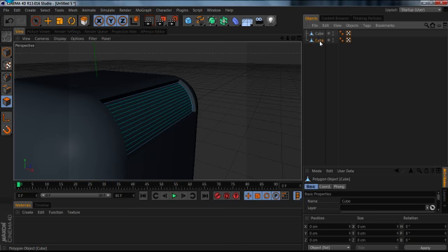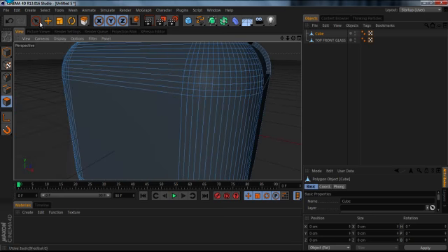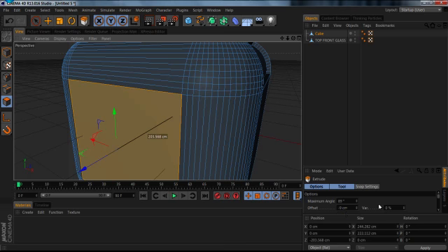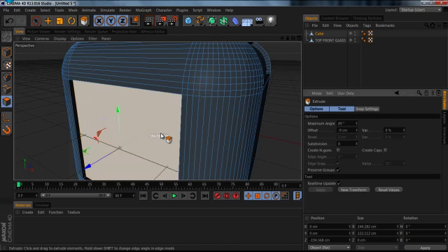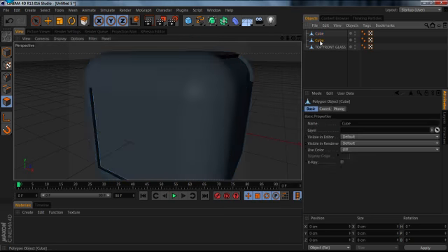So what I'm going to do is rename that to be the top front glass. Next, I'm going to make another selection, which is just right there, using the live selection tool, and I'm going to extrude that as well to -9 centimeters. And then I am going to split that as well, and name that the right big glass. I'm just going to name it anything.